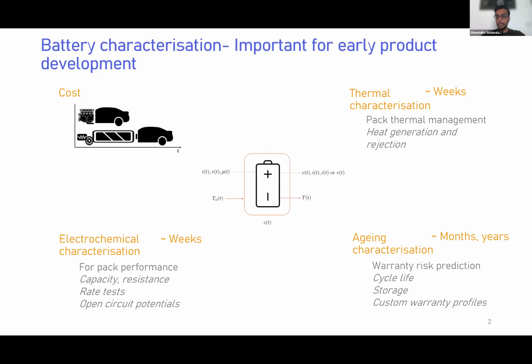It could be in the order of months or certainly several years as well. And that's to understand the warranty risk predictions of the subsequent battery packs. And this is where you would do lab-based tests on cycle life, storage aging, or run custom warranty profiles for the different applications.